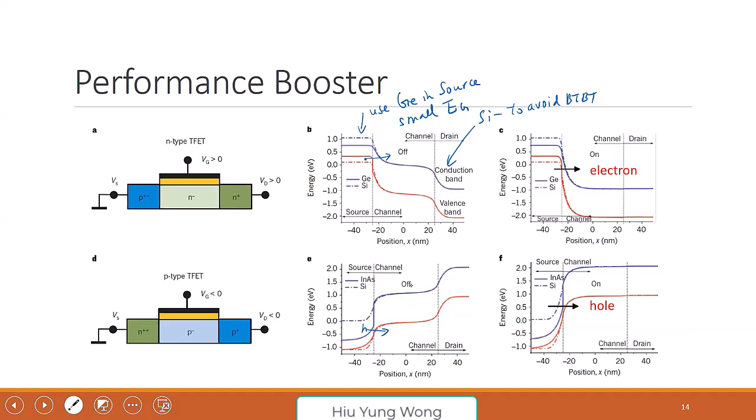Yeah, I guess what I was thinking is if you're going smaller, you have to work with the physical problems that you're presented, which is tunneling and traps. So I thought that the tunnel FET would be the solution to smaller sizes, below 7 nanometer, for example. Yeah, but this is like 100 nanometer, right? You can make it smaller, but why do you think the trap is going to help?